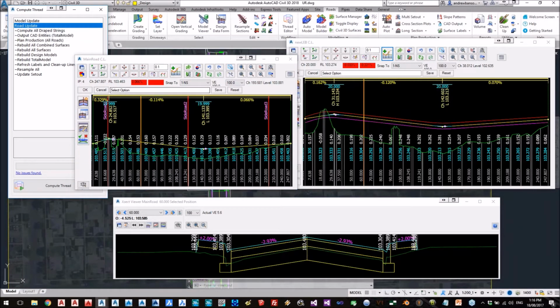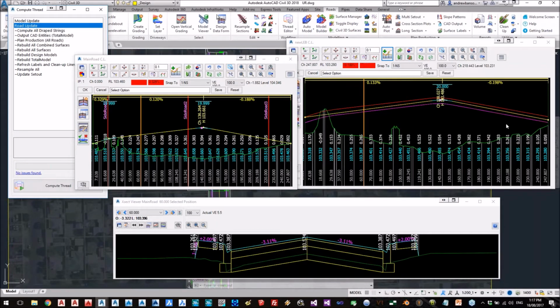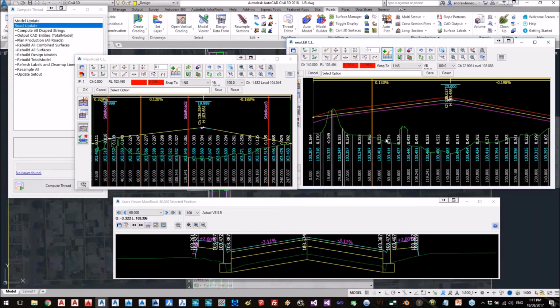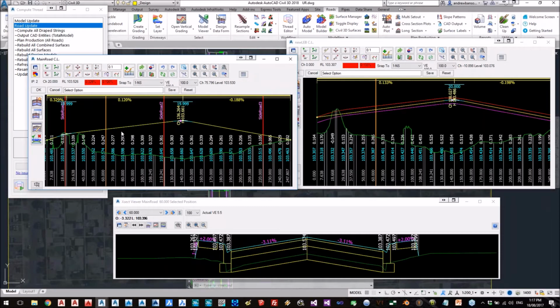and click on Run Thread, you can see now that my design here is updated of my curb, and I'm now getting suitable crossfall. So let me just do that again. This time I'll change the main road, and let's lift it up so you can see that I'm getting pretty ordinary crossfall there. Alright, then I right click and run the thread, and the vertical geometry is processed. Now not only has that happened on the left hand side string, but it's also updated on the right side string as well. Let's do something to make it look a little bit more obvious, and something that's quite cool.